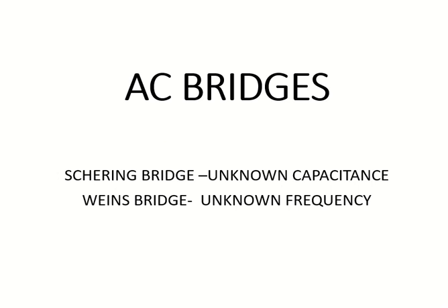We discussed AC bridges in the last video. So we have studied Maxwell's bridge, the Maxwell inductance bridge and the Maxwell inductance capacitance bridge. Both are used for measuring unknown inductance. Next we can study two other types of bridge, the Schering bridge and the Wien's bridge. The Schering bridge is used for measuring unknown capacitance and the Wien's bridge is used for measuring unknown frequency.